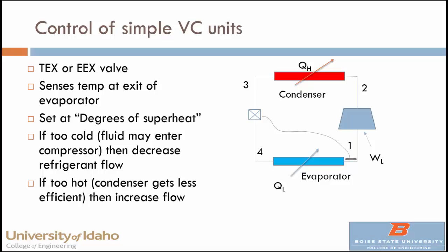That assures that you've always got vapor going into the compressor, that you don't have chunks of fluid going in there. So if it gets too cold and it's not all evaporating, then there might be fluid in the compressor, so it decreases the refrigerant flow, giving it more time to evaporate.